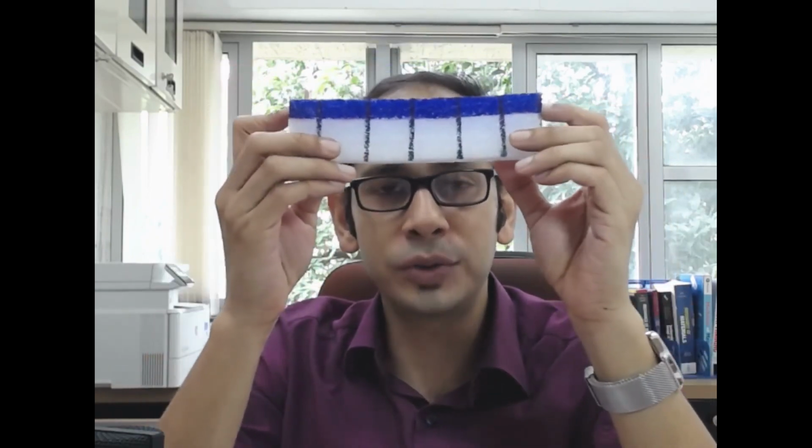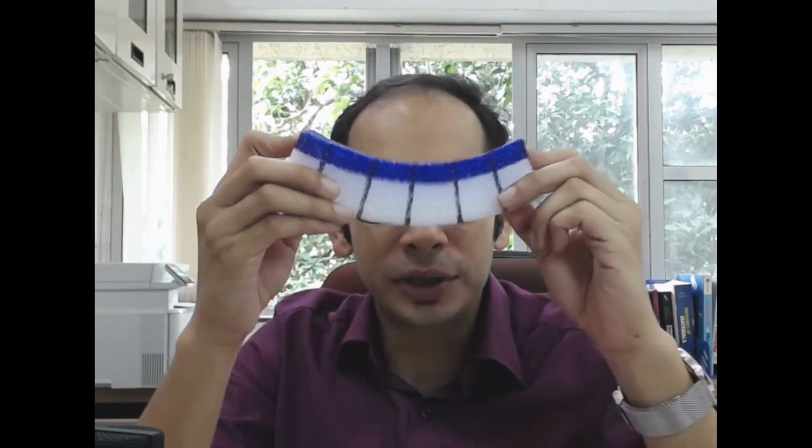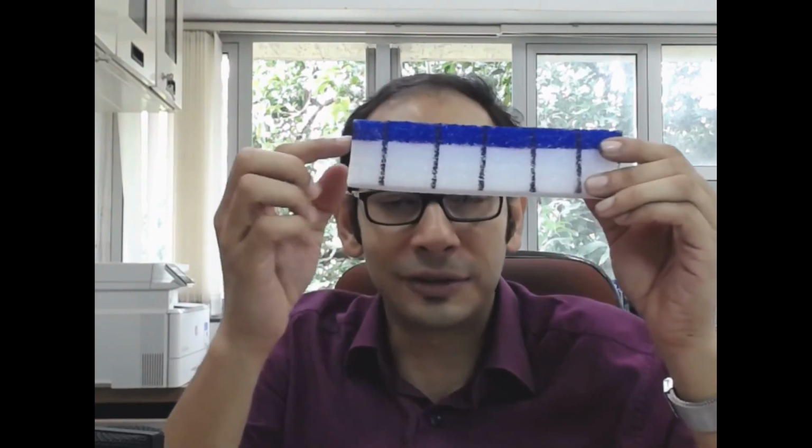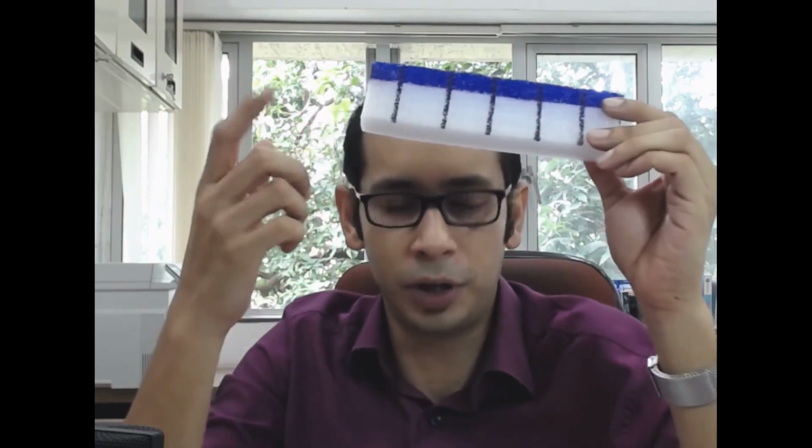What we are going to see is whether the formulas we derived for bending are valid for these beams. If they are, how do we compute the stresses if this beam is subjected to bending? Does the assumption that plane sections remain plane remain valid? And how do we compute the stresses at the interface, and at the top of this beam, which is made of a different material than the bottom part? This is the overall objective of this particular lecture.